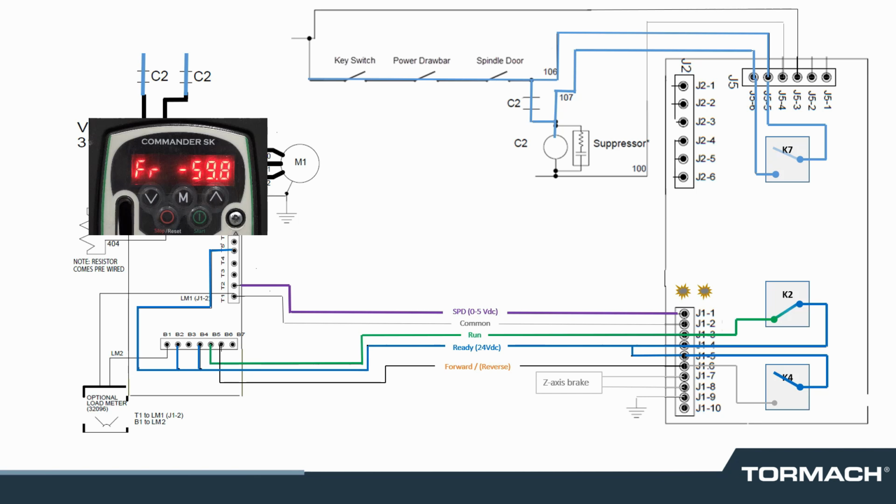A similar circuit on the machine control board sends 24 volts DC back to the VFD through the closed contacts of relay K4 connected to J15 and J16 as the forward reverse signal. When present, the spindle drives forward. When absent, the spindle reverses. The VFD display will include a minus symbol with the frequency and speed when spindle reverse is desired.